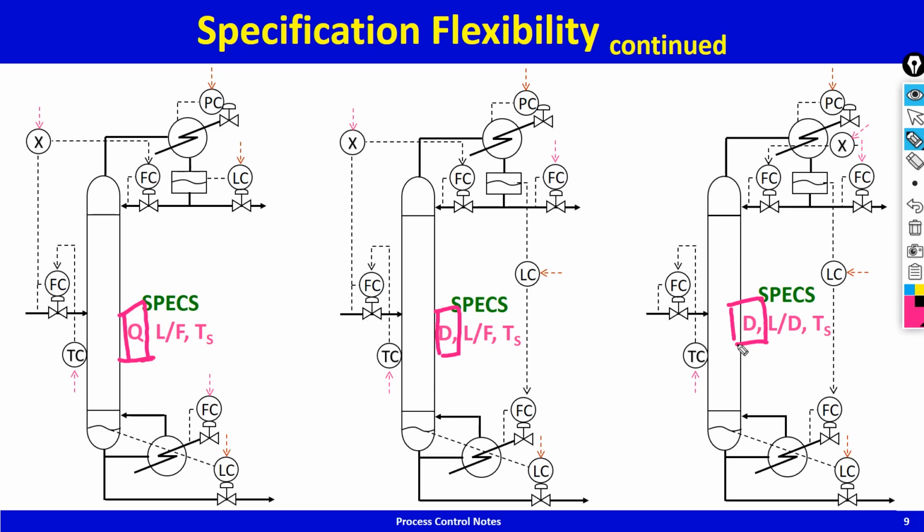So this is what is used for production rate changes here, this is what is used for production rate changes in the second case, and this is what is used for production rate changes in the third case. In the previous slide, it was feed rate that was setting the production rate. So the point is that where you set the production also has consequences on the control structure.